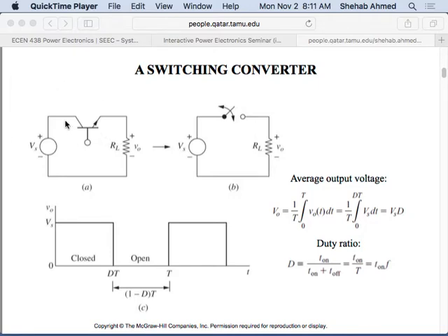In a switching power converter, we operate these switches like an ideal switch. So it's either on with a very low resistance or off with an infinite resistance. If it's a very low resistance, then the losses are quite low compared to the case of the linear regulator. But because we end up with a waveform that is sort of a pulsed shape waveform, which is not acceptable to our loads in most of the cases, right? If our load just requires some average power, is this waveform okay or not? If a load just requires an average value of voltage, it will filter out the voltage by itself, right?